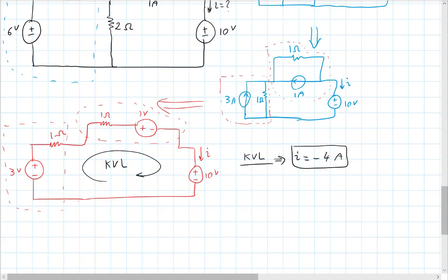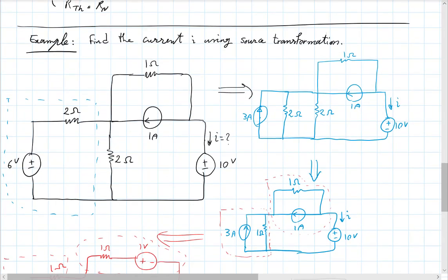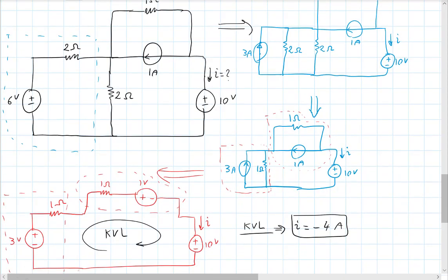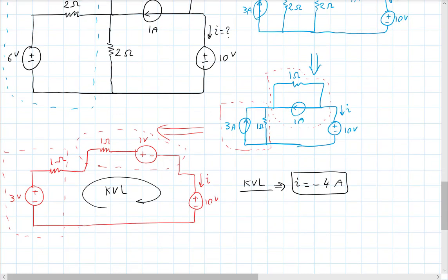But primarily, what's of interest is, again, when you're looking at something from the outside. And so with these steps of turning, it's a little bit of magic, you might say, turning this initial Thévenin-like circuit to a Norton equivalent allowed us to combine these resistors and then turn that back into a Thévenin later, and also turn the top one into a Thévenin, and all of a sudden the circuit became one loop.